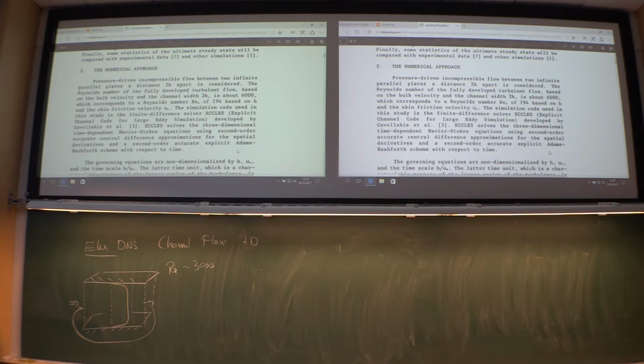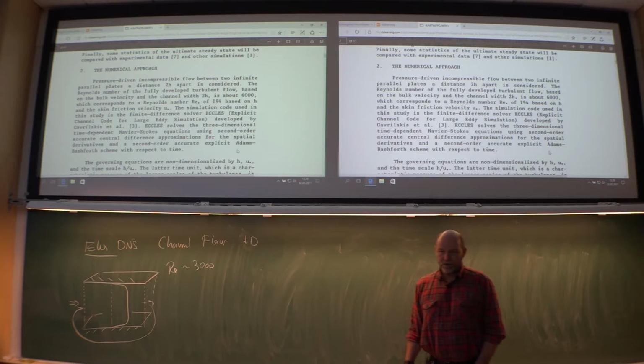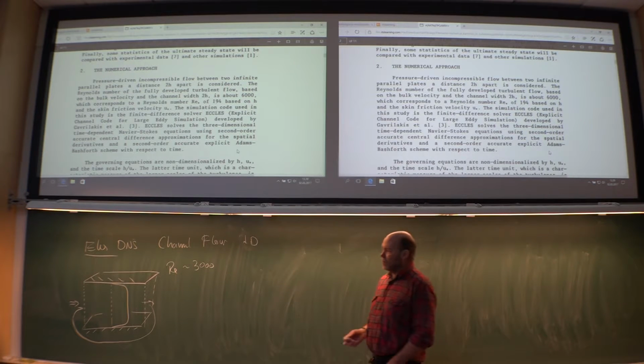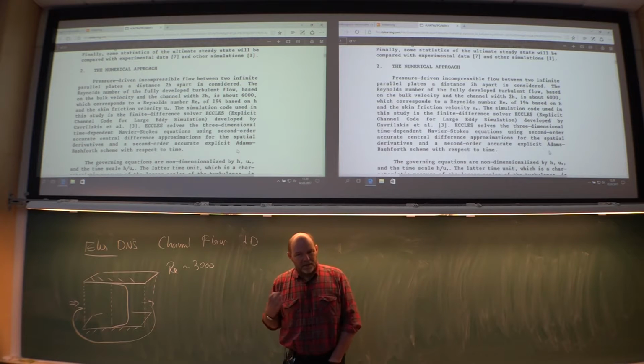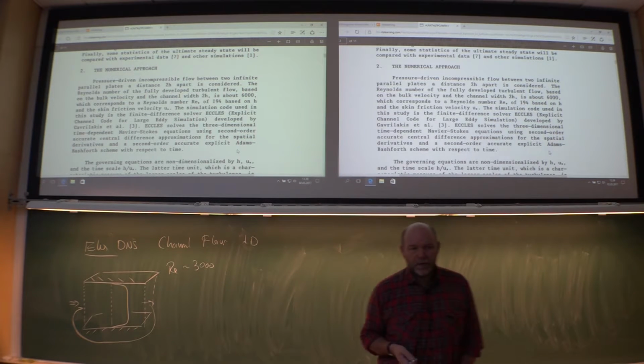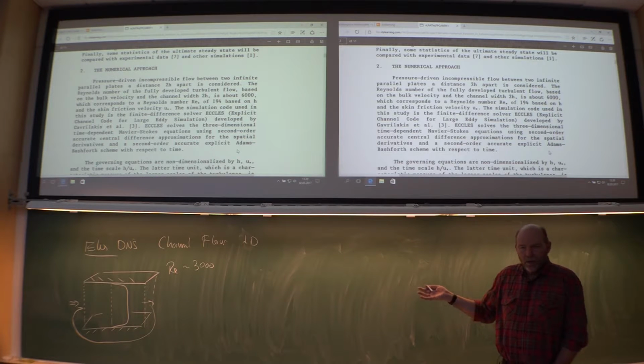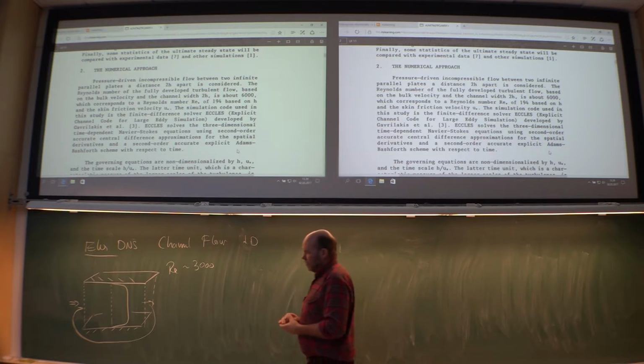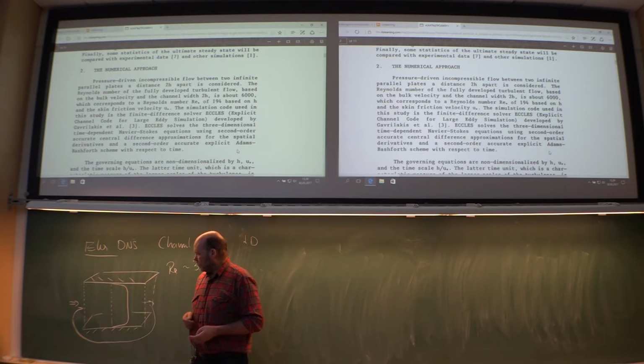And the first attempt that I did was just to say everything was zero, and then you set up a driving force, and then you just let the flow evolve. And when I did that, I wasted I don't know how many thousand CPU hours, and I got a laminar solution. Although the Reynolds number was turbulent. But remember, a laminar solution is still a solution of the Navier-Stokes. It just should be unstable. So if anybody has slammed the door or shaken it a little bit, it should trip and become turbulent. But it didn't by itself, so I had to help it.